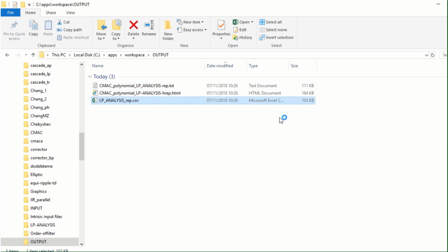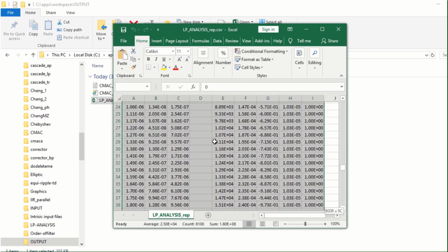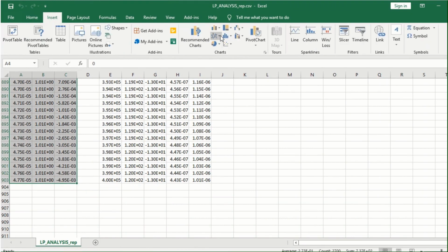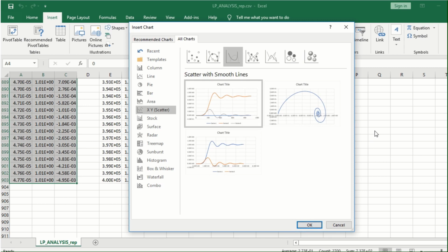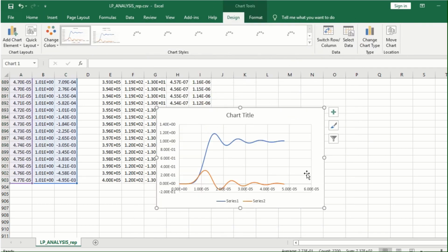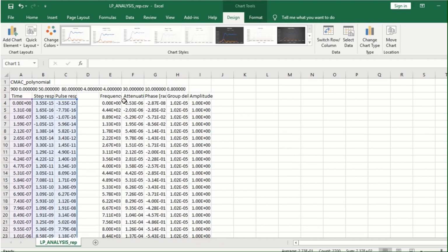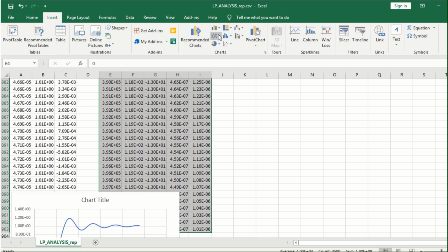Here it is. And here is the step and the pulse response of the ninth order least square monotonic filter. As you can see, the undershoot here is much smaller, which makes the eye much more open and more acceptable for pulse transmission implementation. Here will be shown the frequency characteristic.